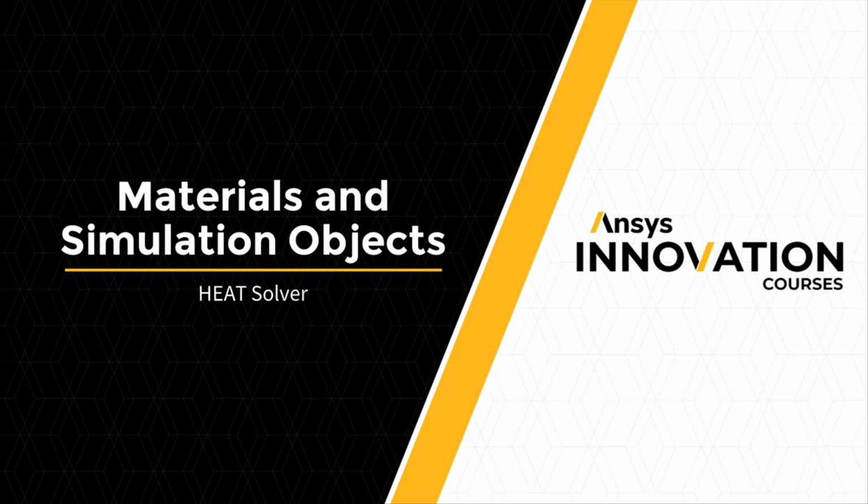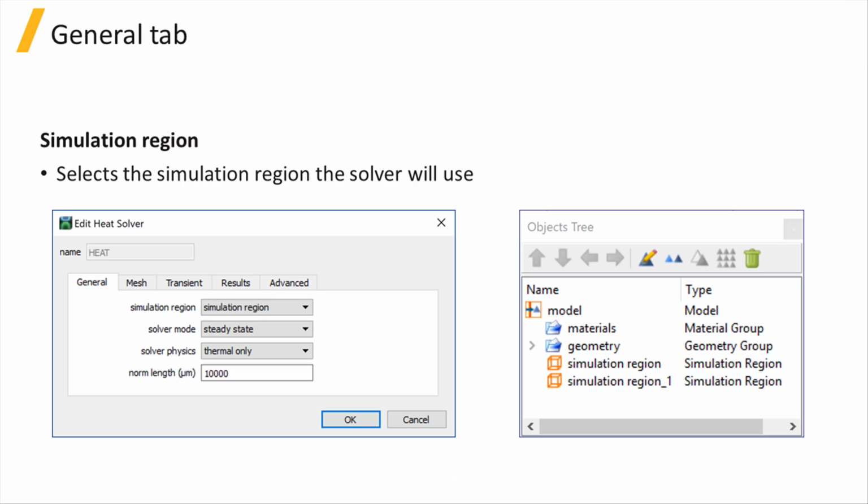In this unit, we will explore various settings available for the heat solver. Under the General tab of the Heat Solver Property Editor window, the Simulation Region parameter selects which of the simulation regions from the objects tree will be used by the solver. Note that only one simulation region can be assigned to a solver at a time.